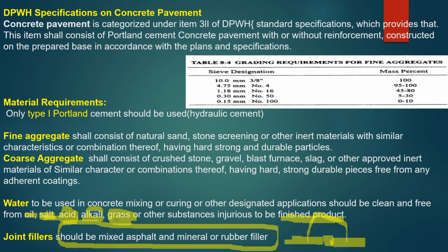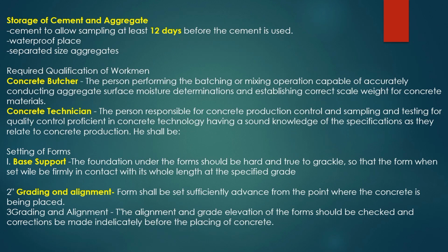Okay, we'll proceed to the other slide. The other slide is the storage of cement and aggregate. Cement to allow sampling at least 12 days before the cement is used. So, allow sampling 12 days before using the cement. The other one is the waterproof place.